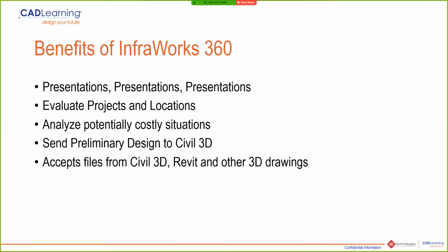So where do you use it? I use it for getting everything before the survey comes in. And then I'll send it to Civil 3D and hope, and this is the biggest problem I think I have with surveyors right now, that they don't always survey in their coordinate system. You hope that what you get from the surveyor is in the right coordinate system, because InfraWorks 360 is so dependent on coordinate systems, it's not even funny. So you hope that when you send it across, it marries up. If not, I'm adjusting stuff.